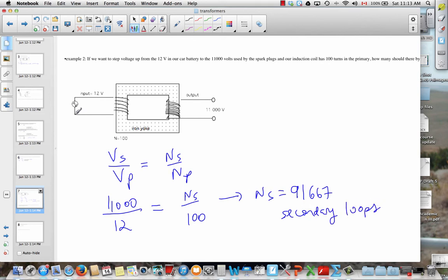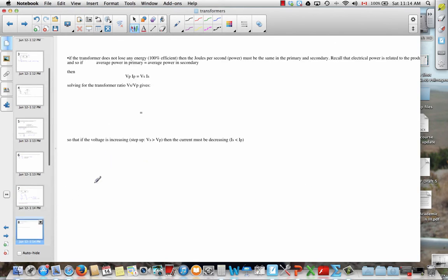Now you may say, hold on, the car battery is actually DC. How can it work in a transformer? Well, there's a very clever little circuit here where there's actually a little switch that opens and closes. And so that DC voltage decays when the switch closes. And it's the decay that gives you a steep rate of change that gives you the change in flux. So it's cleverly done. And that analysis is essentially correct.